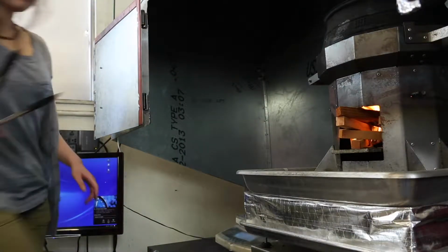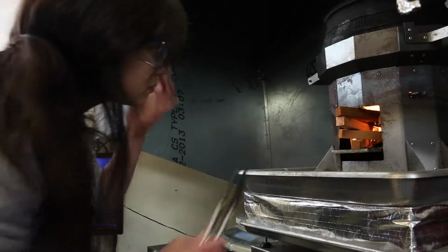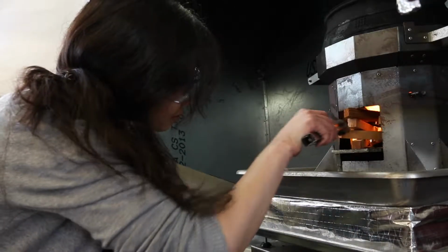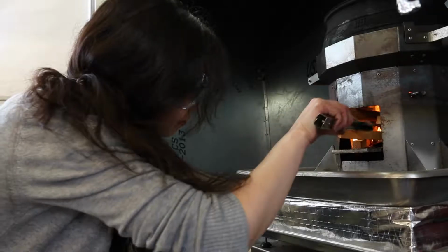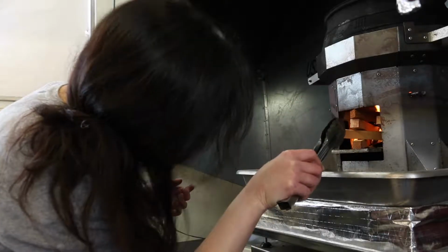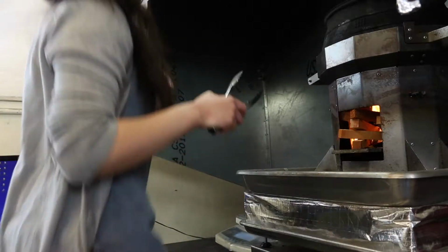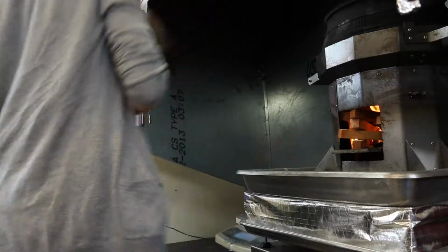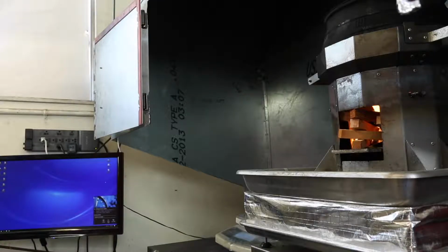Over the course of this test, the fire tender strives to feed wood sticks to the fire at a rate that maintains a consistent firepower. This particular testing event will end once the water reaches the boil. We note that at this elevation and with this particular thermocouple probe, boiling water corresponds to 99.5 degrees Celsius.